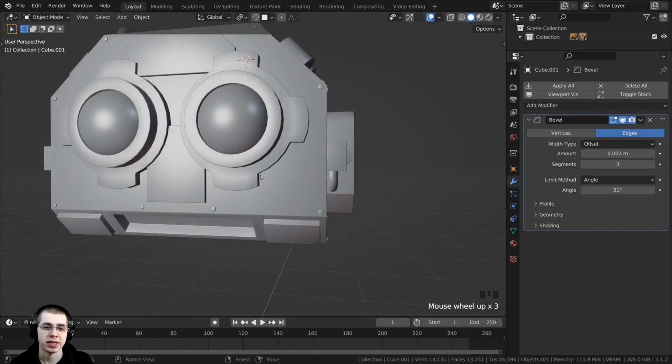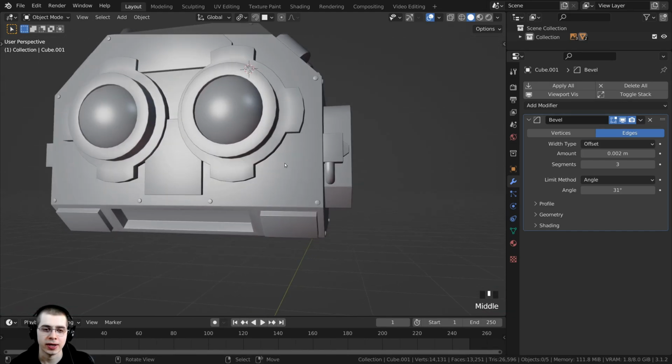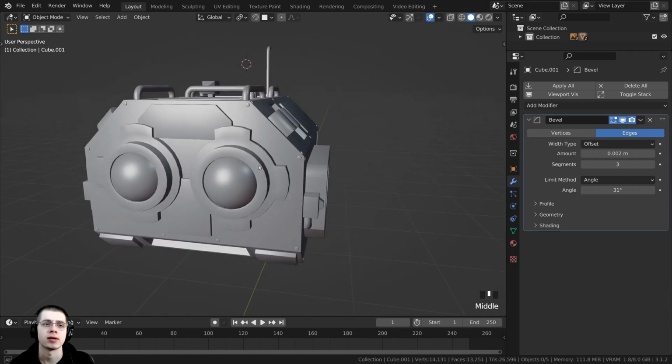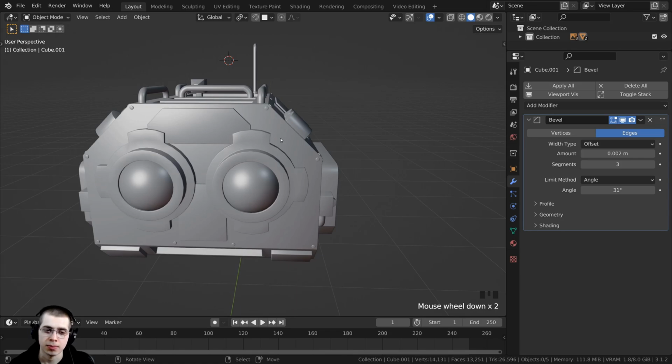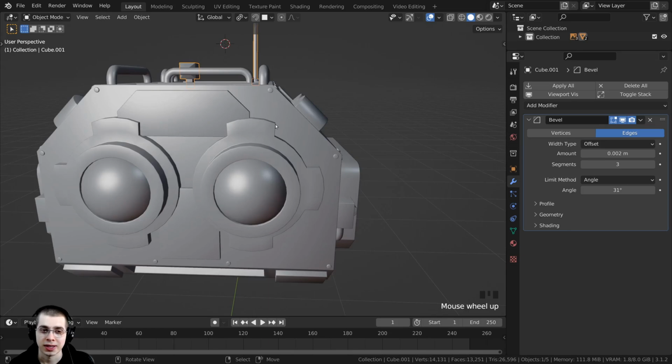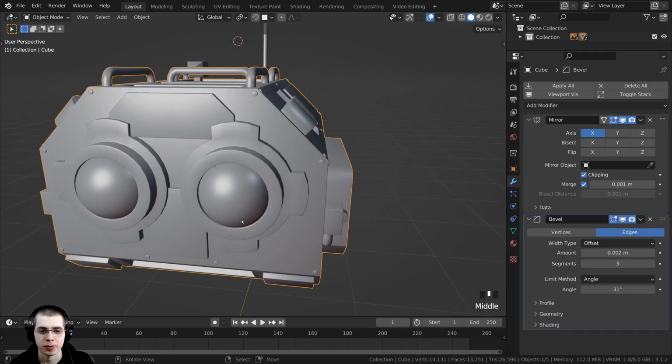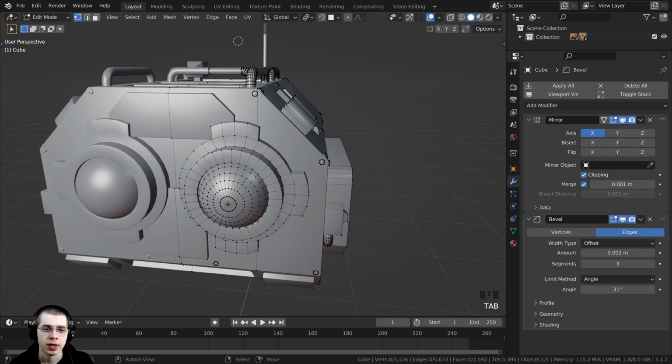All right, so I now want to add a little light, which is kind of right here on the side of the robot's head. So I'm going to be using this eye object that we already modeled, and I'm going to again break it into its own object and then join it together into this object. So let's select this object right here. I'll press the Tab key to go to edit mode. Just press the A key to make sure everything is deselected.